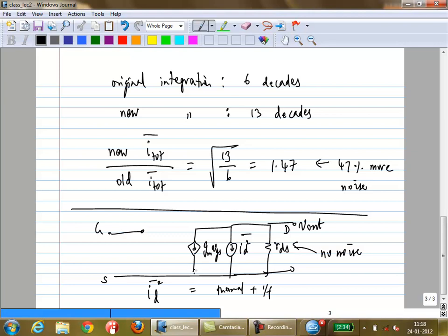If you didn't have a signal here, let us say you have a common source amplifier with this grounded, and you're applying the signal directly without a source resistance, you would short this to ground. What is VGS? 0. Therefore, this signal goes to 0. You will still have thermal noise, right? The noise is independent. So the noise is something added extra.